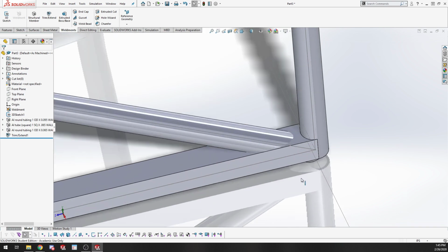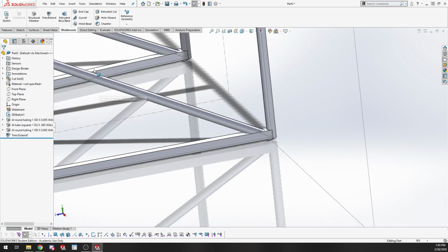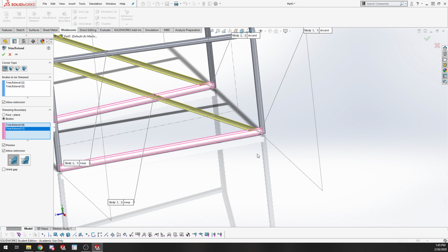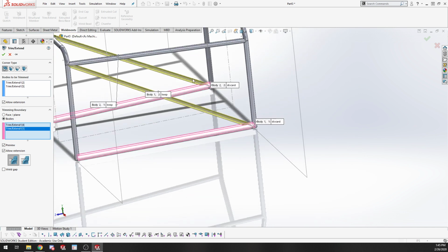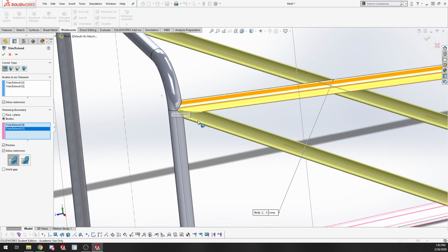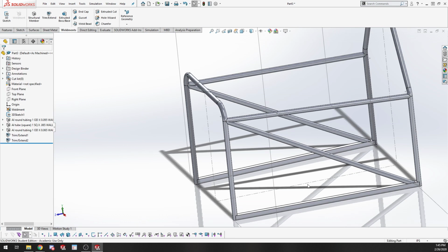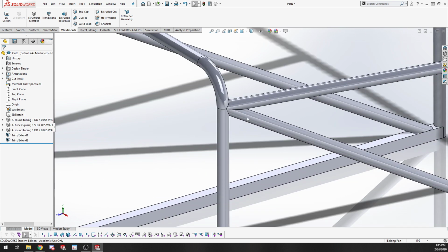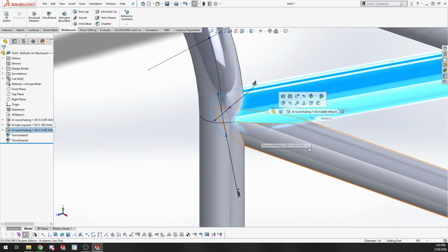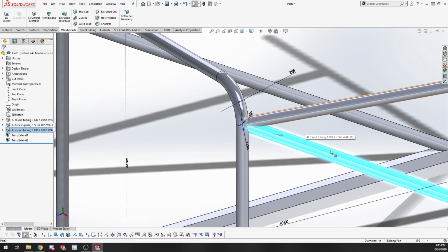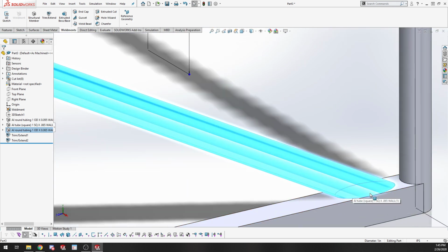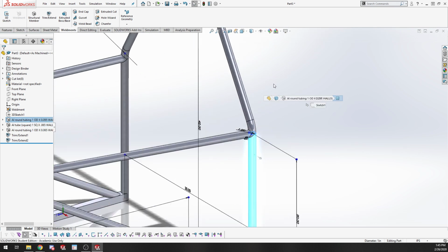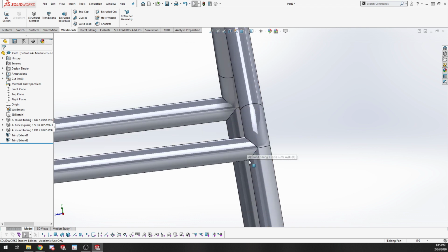And then if you remember down here, this tube didn't get trimmed against that one, so we'll make another trim. Trim these two bodies against these two. Cool, and it removes those for us, automatically picks those out, and now we should have our completed chassis. I'll go ahead and hide that sketch. So zoom in here, there's one body coming in, this body gets trimmed against it, down here gets trimmed flush against this square bit at the bottom, and then our roll hoops are just one continuous body all the way through. Everything's nice and cut through.